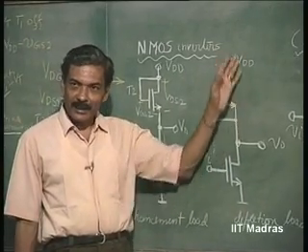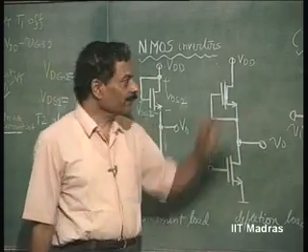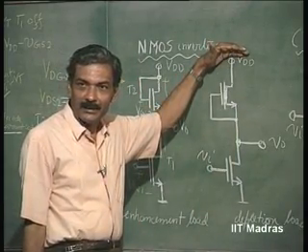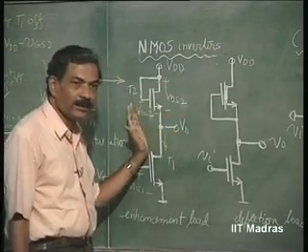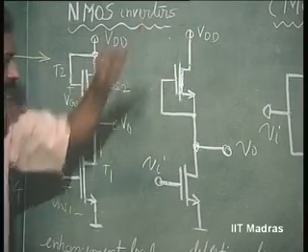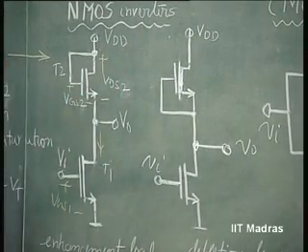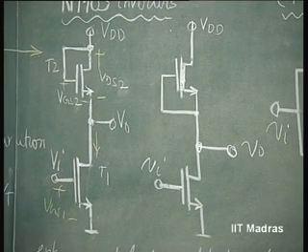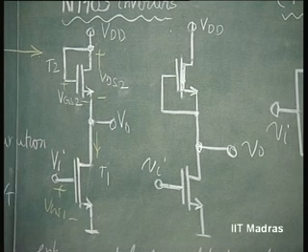Okay. When the current is 0, the voltage drop is 0. That means, the voltage here can start now from VDD itself. So, between this and this, you have this disadvantage here, right. So, it will straight away start with VDD. So, its transfer characteristic, now if you plot, it is going to start at VDD.